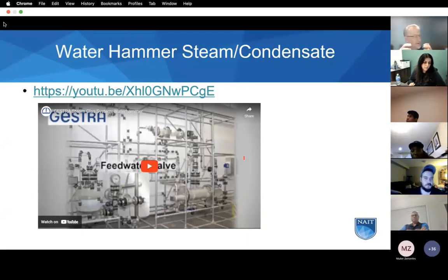The bubbles, a lot of water can be collecting in a steam header if there's a trap that's malfunctioning or left blocked in. There's not enough traps in your system. Steam bubbles, water can fill up the steam line enough to trap some bubbles, and then when those bubbles collapse, there's great forces when those bubbles collapse as they condense.